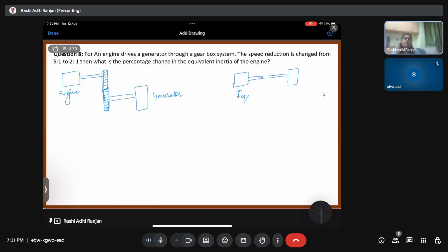Like for example, we discussed the case of a simple pendulum, where the pendulum was oscillating in the x and y plane, right? But it was considered a single degree of freedom. Why? Because the bob was connected through a thread or a rod, and the length of the rod or thread was not changing with time. So we had the relation x square plus y square is equal to L square, by the right angle triangle. Now for every x, I can evaluate y by that relation. So technically, I can convert it into a 1 degree of freedom system.